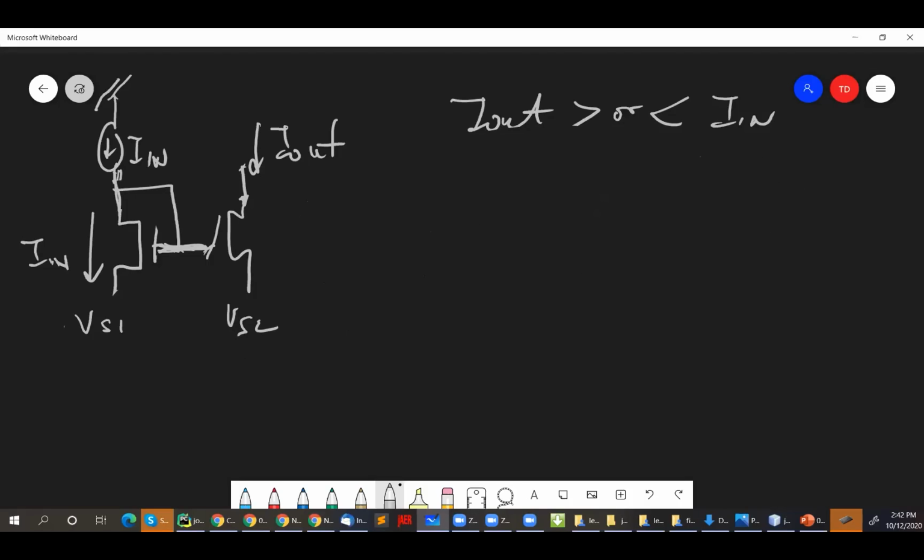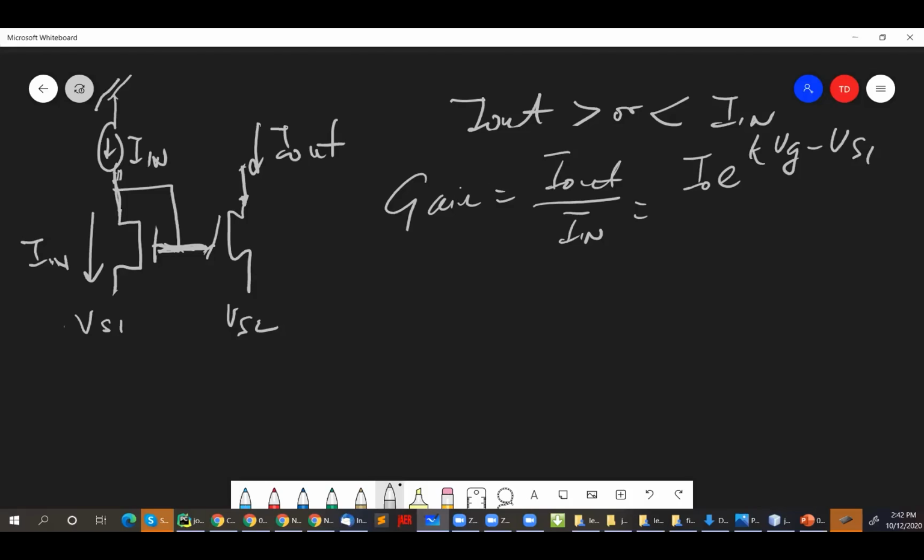So that means your gain now, remember, is I out over I in. And so that would be I naught e^(kappa VG minus VS2) for the output transistor, over I naught e^(kappa VG minus VS1) for the input transistor.